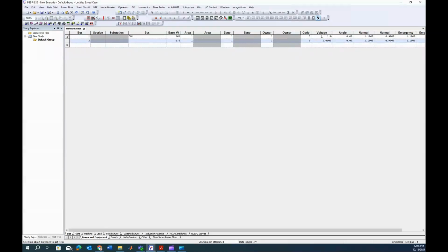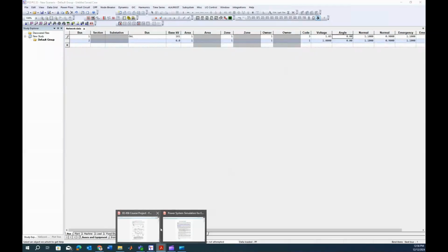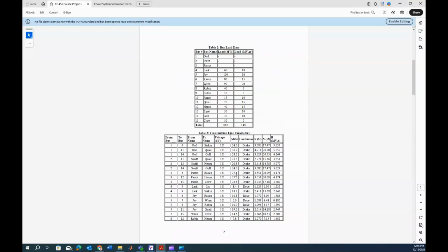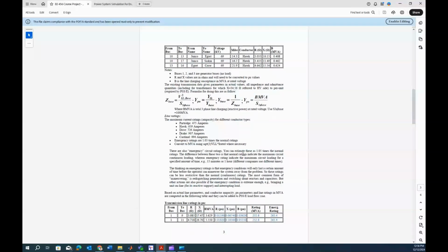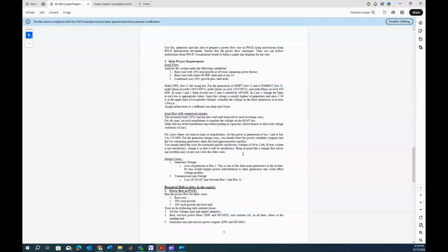So you can take 1.03 or 1.04 because we clearly mentioned in that reference document that you can take voltages for the generators between 1 and 1.04. You can have a look at that data here, where we mentioned that you can take the voltages somewhat like this.